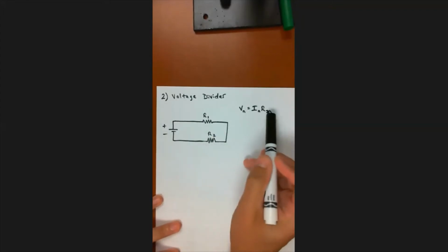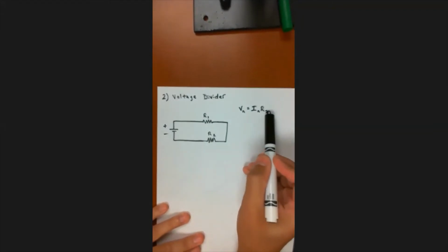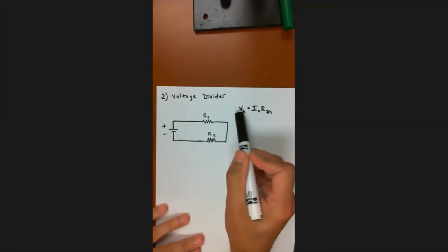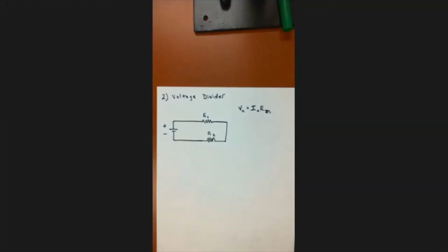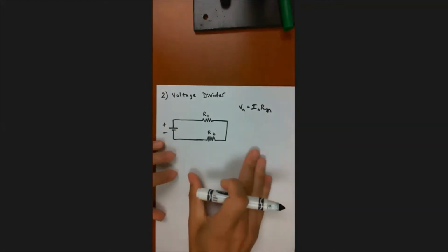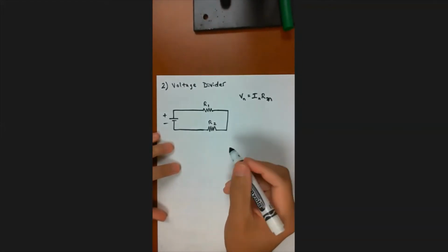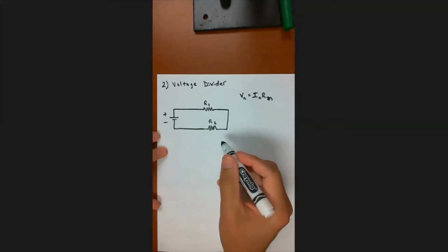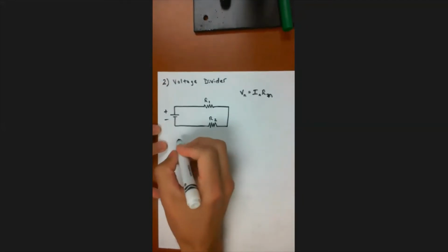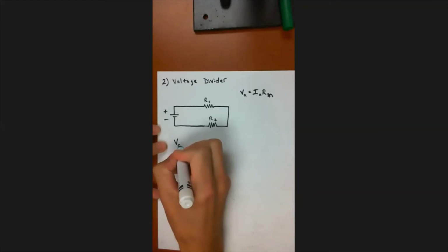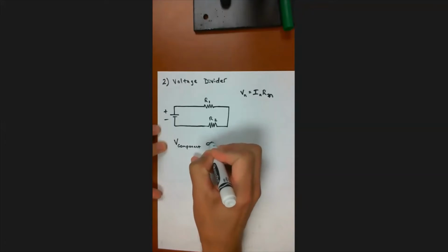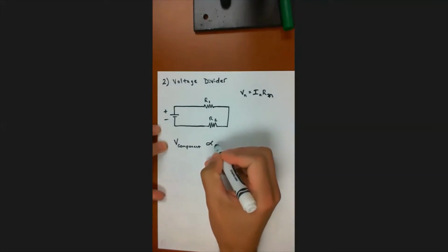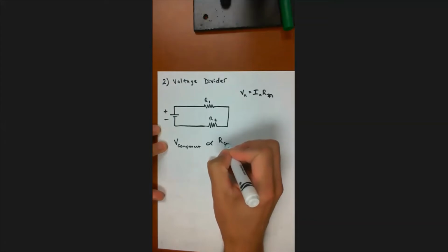Because when I plug those R's in, if R1 is going to be much larger, that's going to force V1 to be much larger than V2. So whichever one has the larger resistance is going to have the larger voltage drop. This is actually kind of a law, and we can put this into an equation. In general, this is not quite the equation yet, but we could say the voltage drop across a component is proportional to the resistance of that component.